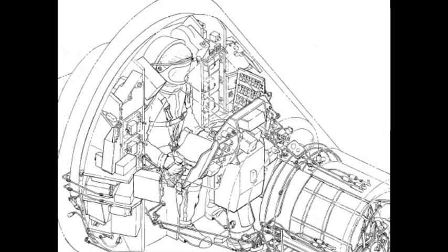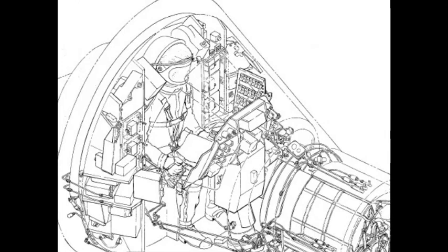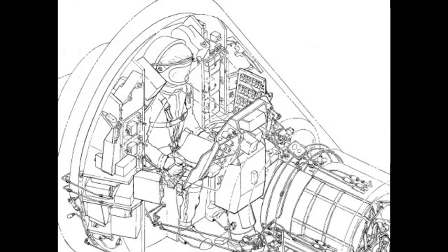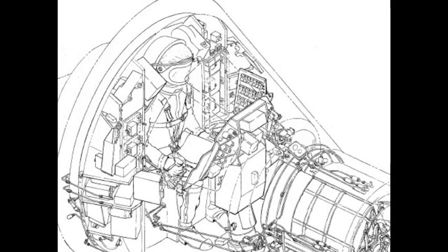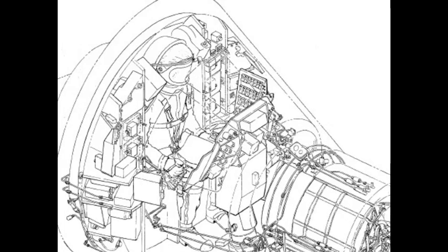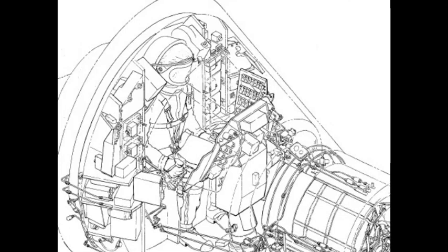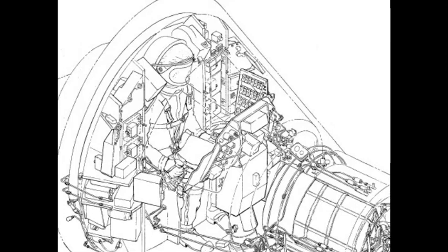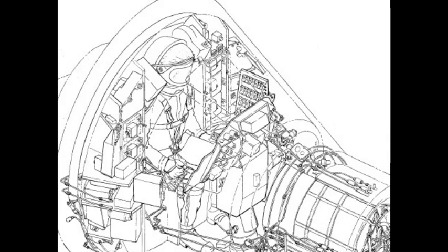2.8. An observation window, figure 2.3, located on the afterbody conical section, is provided to enable the astronaut to view the capsule exterior. The window, located above the main instrument panel, consists of an inner and outer assembly. The inner window assembly is made up of 3 glass panes sealed in a titanium frame that is attached to the cabin wall. The panes are independently sealed to provide a pressure seal between the panes.